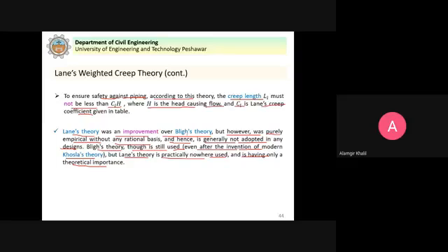In Lane's theory, he just gave weightage to that, the rest everything is the same as per Bligh's theory. So Bligh's theory was used from 1910 to 26, 27 for the structures. Some were successful, but some larger structures were not successful. So then investigations were carried out to find what the problem was, and that led to what is known as Khosla's theory, and that is used for modern design of the weirs and hydraulic structures.